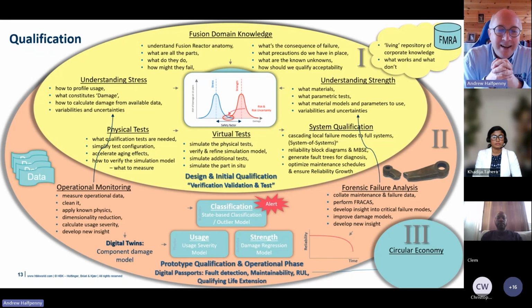Now, my little system here, I've got two different approaches. At the top, I've got a classification-based system. So this is using machine learning type classifiers. And what it's doing is actually novelty detection. If I've got 200,000 electric vehicles driving around, I can't go in on a Monday morning and pick one at random. I need a computer to say, this is worth looking at. I've not seen this before. So this is what classification does. It just looks for something which is anomalous, a novelty, an outlier, and says, you might want to look at this first. So it raises alerts.